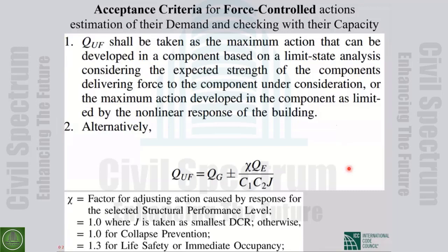If it's less than the M value assigned based on the condition and the performance level of the element, it is okay. Yes, we can see the amount of damage in this element, but using the M factor, we say that as long as M times capacity is more than demand, it's okay.